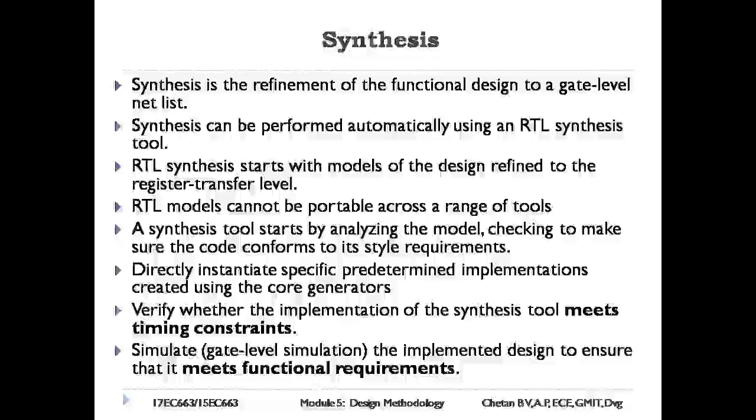The process of translating the design into a circuit of library components is guided by synthesis constraints. Such constraints include bounds on clock periods and propagation delays. The synthesis tool uses the constraints to choose among alternative implementations.